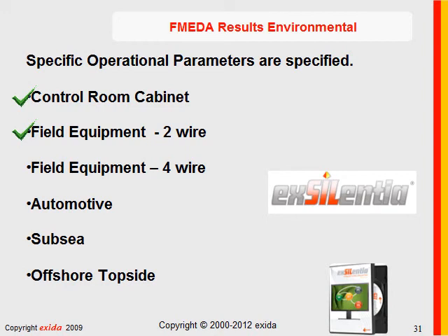Why two-wire devices? They have very low power dissipation, and there's very little internal self-heating. Four-wire field equipment, some of which dissipate 10 or 20 watts, in which case you get a pretty high temperature differential between the outside ambient temperature and inside the case.